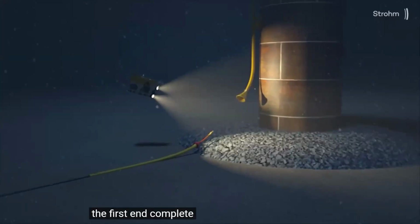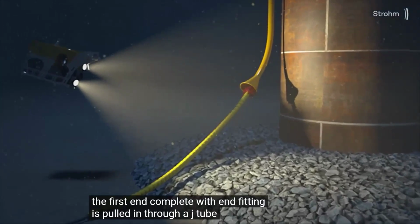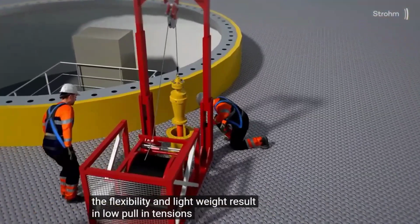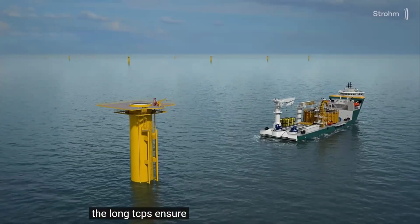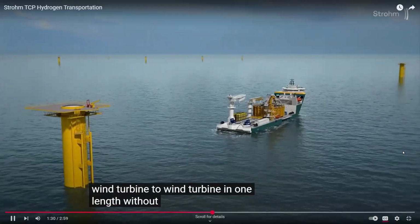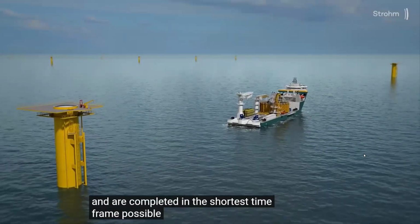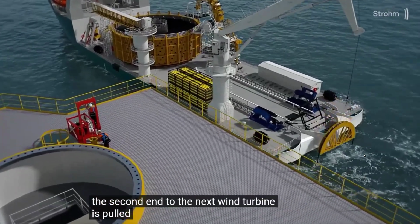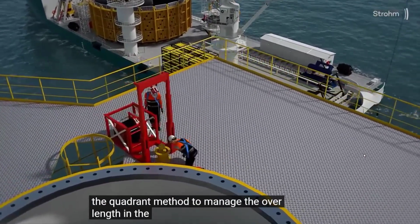The first end fitting is pulled in through a J-tube. The flexibility and light weight result in low pull-in tension. The long TCP ensures installation from wind turbine to wind turbine in one length without intermediate connections, and is completed in the shortest time frame possible. The second end to the next wind turbine is pulled in through the J-tube using the quadrant method to manage the overlength in the pipe.